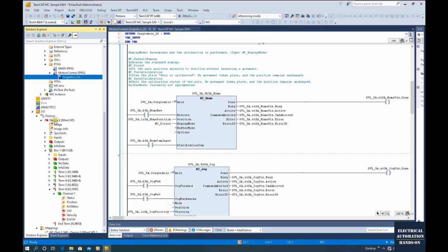Currently, for this EtherCAT device, this KL2541, we are using the BK1120 as an EtherCAT station. In this station, there is one module, the KL2541. For the controller, I'm using my laptop, and my laptop is connected to the BK1120 using an Ethernet cable. The protocol we are using is EtherCAT, because the BK1120 is an EtherCAT station interface module.